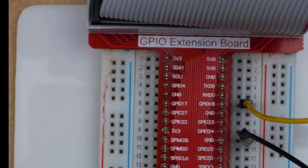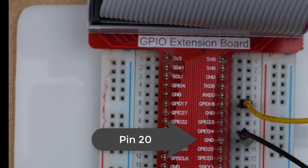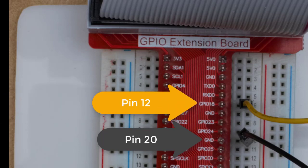As before, we will connect the LED black wire ground to the GPIO extension board ground. We'll also connect the yellow R pin wire to physical pin number 12, GPIO pin number 18.